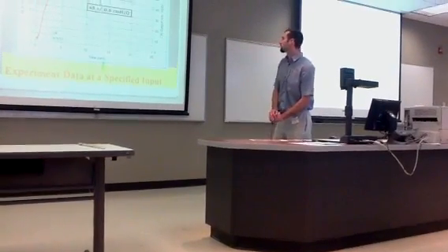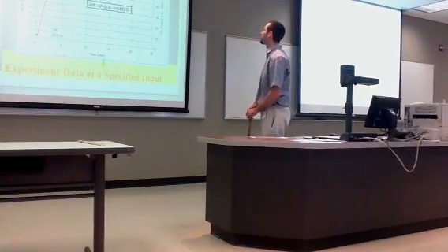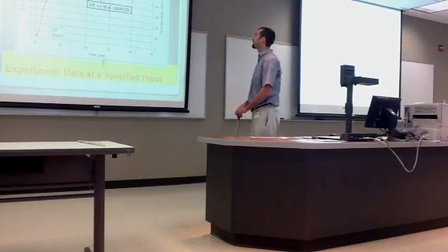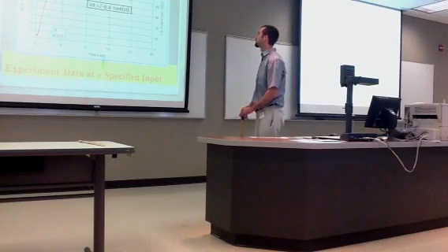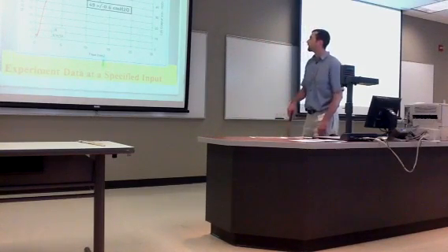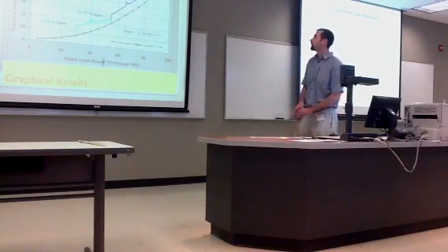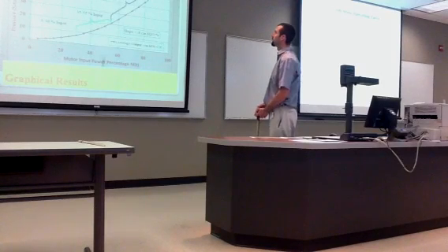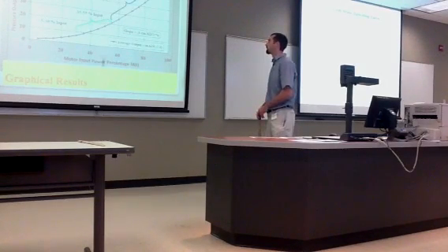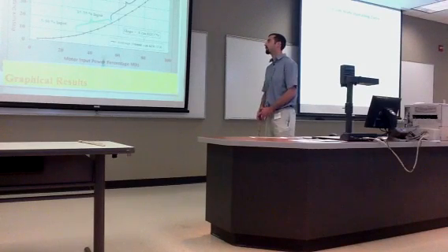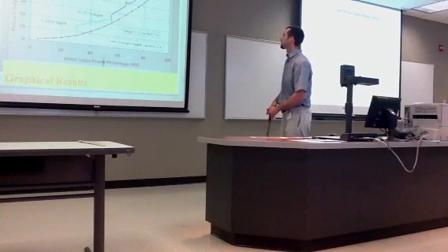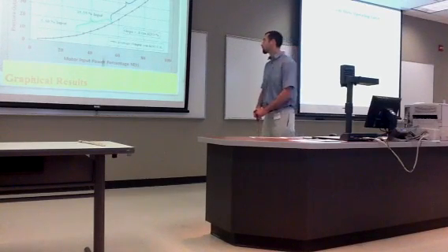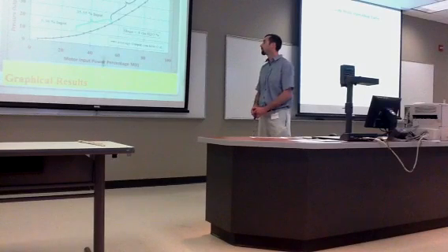This graph shows experiment data at 85% input power. It found steady state at 49 plus or minus 0.6 centimeters of H2O. From the data that we compiled, we were able to form a steady state operating curve with 3 different input ranges, 5 to 30% input power, 35 to 55% input power, and 60 to 85% input power. We found that the slope is 0.8 centimeters of H2O per percent power.